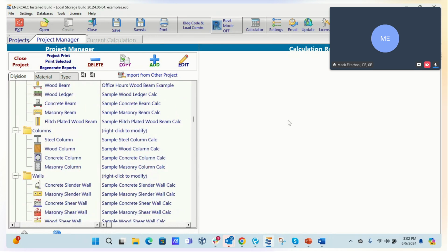when you have a beam that maybe sits on a girder, and then a girder that sits on a transfer girder, and then a transfer girder that sits on a column, normally you will have to grab the reactions manually from beam number 1 to the girder and so forth. So you'd have to carry them down manually. And then if something changes in the first beam, now all of your reactions have changed, and of course you'll have to redo all of that work manually. And a lot of times it gets missed.